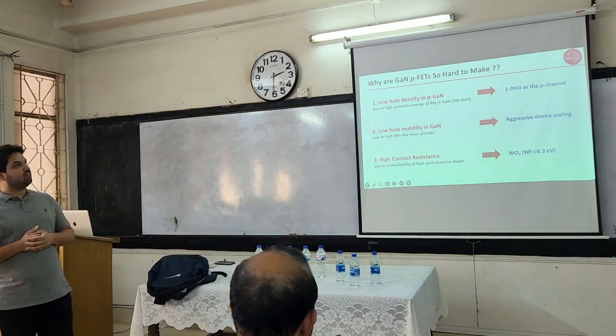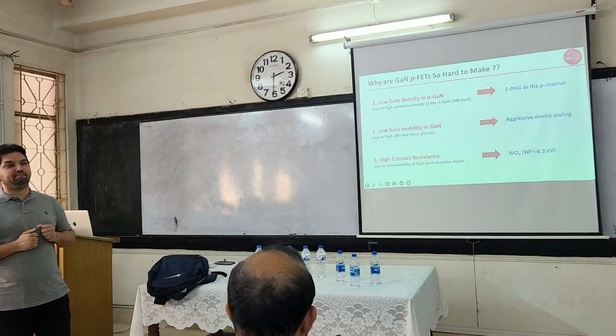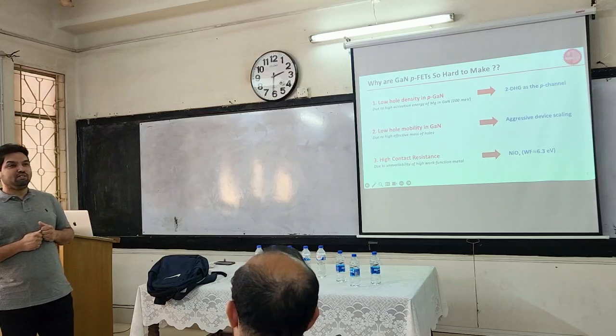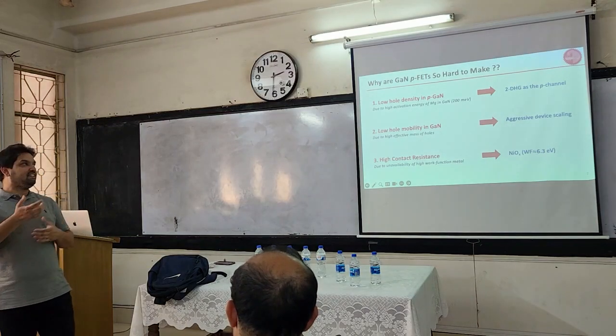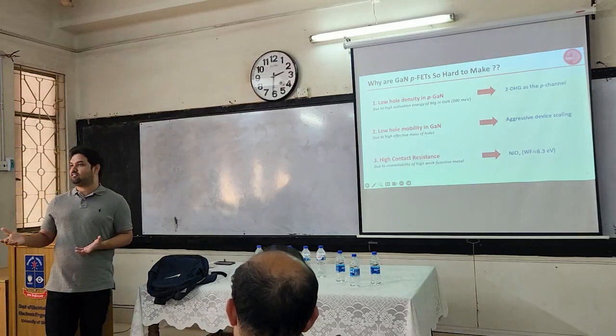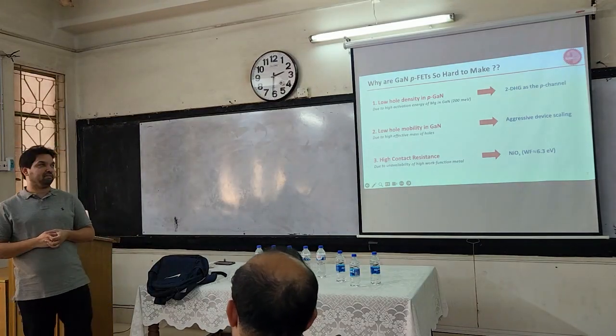Let's see how we're going to do that. We're not going to dope the material. We're going to use the polarization charge to make the holes. So we do some band engineering and try to have the hole gas instead of doping the semiconductor. That's one.